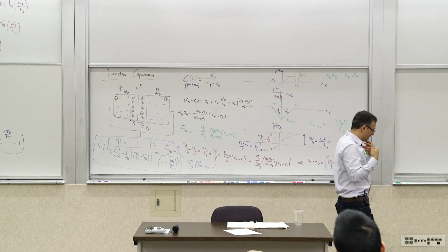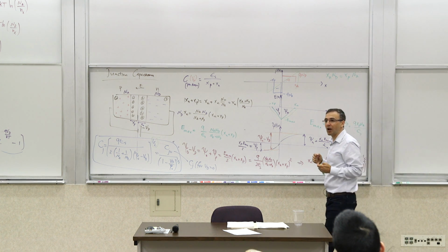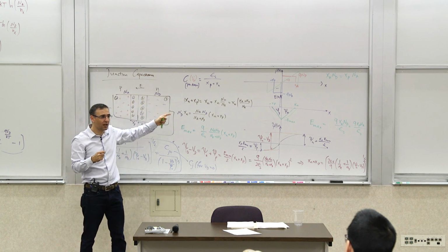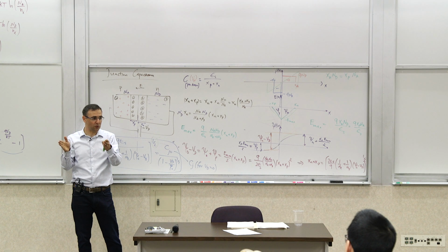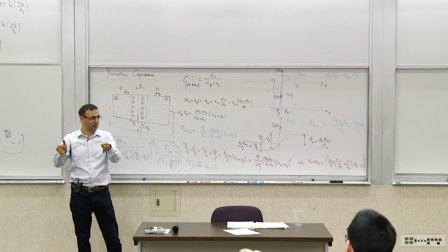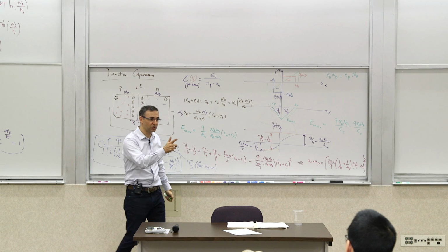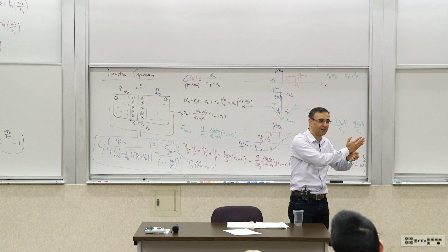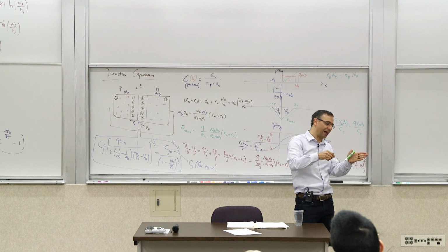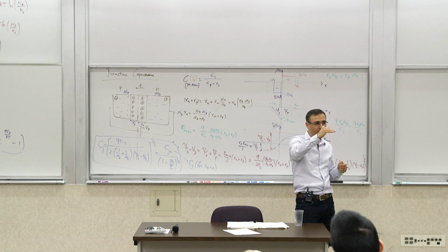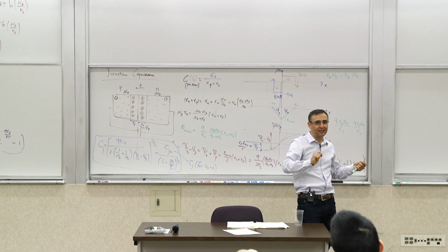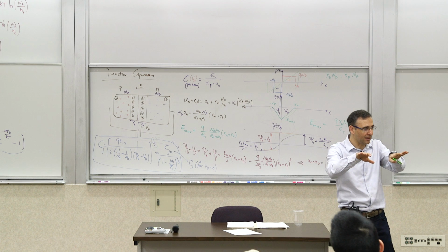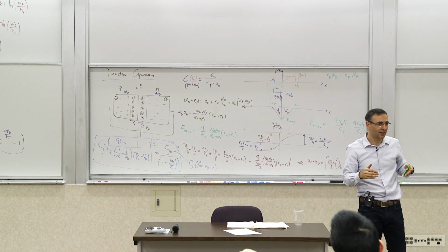Now, today, most of the time, you do it with ion implantation, which basically means that you ionize the carriers that you want. You put them through a particle accelerator. Basically, you just have two charged plates or a combination of them. You accelerate them to a certain energy, measured in kilo electron volts or something like that, and just smash them into the silicon. Now, by controlling that energy and density and the angle at which they come in, you can actually create different profiles at different depths. And then after you do that, you anneal it. Basically, you raise the temperature so these things start jiggling around and then falling into the right place. So the crystal damage that you've done is repaired. And then they will stay there.